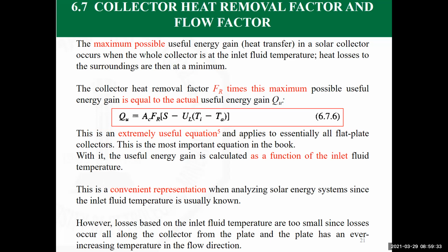This is going to be a general characteristic for any collector. When you are going to buy a solar collector, before buying it, you need the specification sheets, and the specification sheets are going to have the efficiency as a function of the heat removal factor as an important parameter.